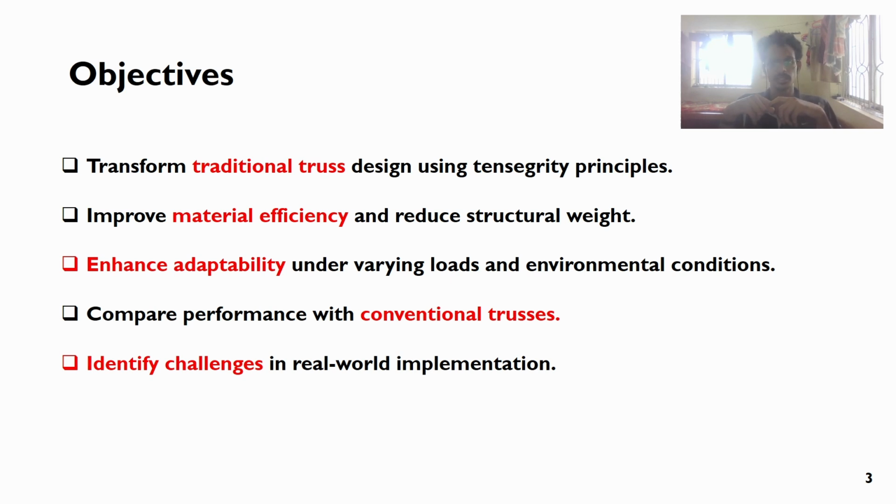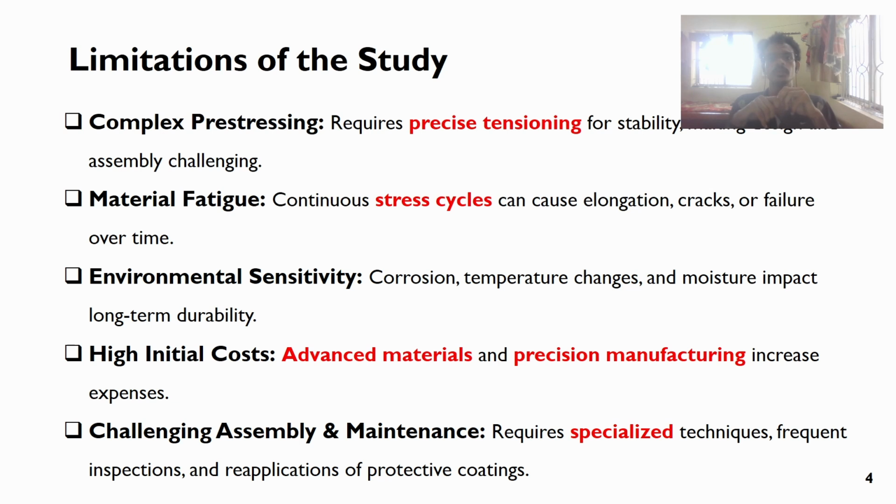Let's identify the real challenges with implementation. When I went through these articles, I understood there are some limitations when you use the tensegrity concept: complex pre-stressing where precise tensioning is required, possible fatigue failure, cracks in the materials, and elongation of materials when tensioning.